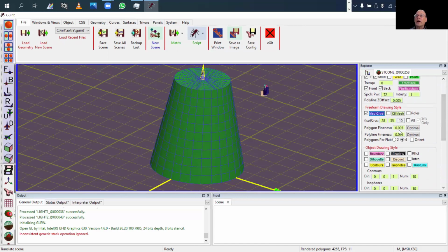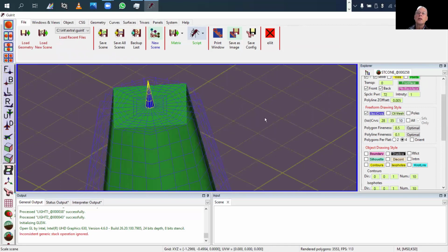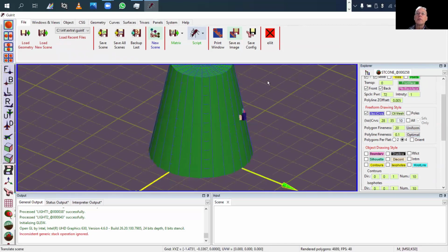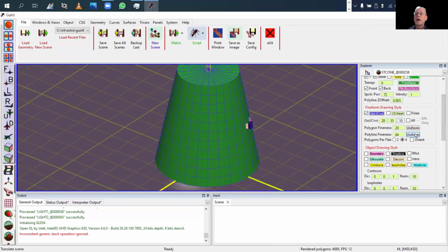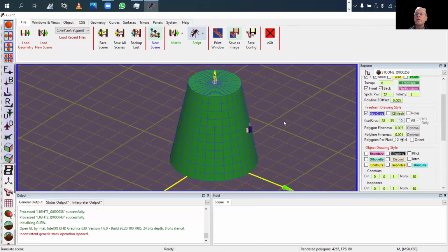And you can change the tolerances. So if I get something really crude, it's going to look really ugly. This is the polyline crudeness. So you see that the polylines are very crude now, the ones that are seen here. So we can change the way we tessellate. There is a uniform tessellation option, which is what we apply now, or there is the adaptive option, which was the default. And we can do many, many other things.